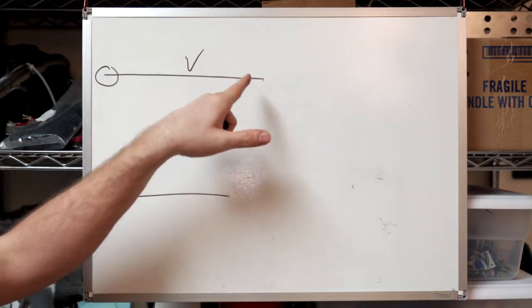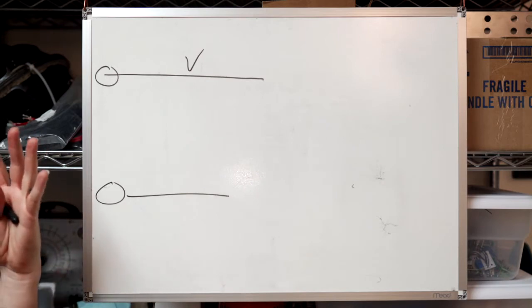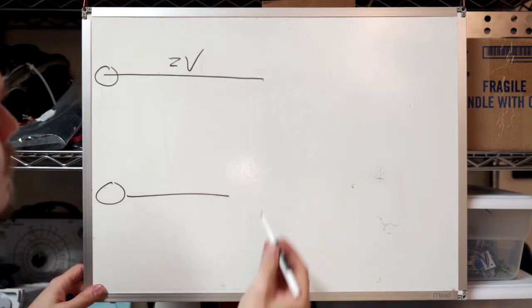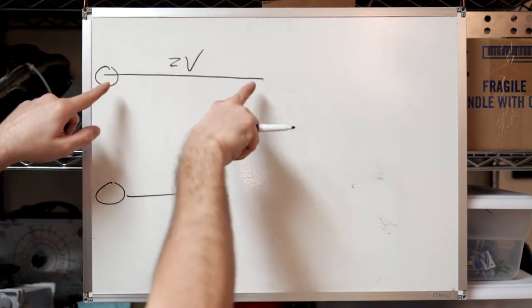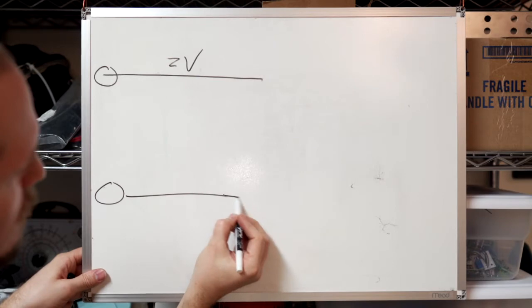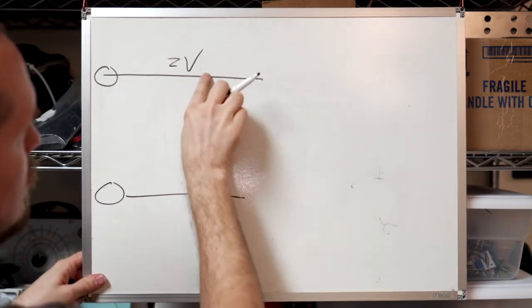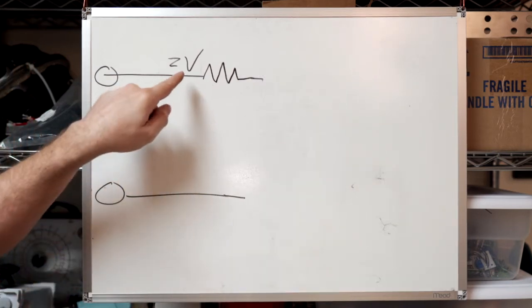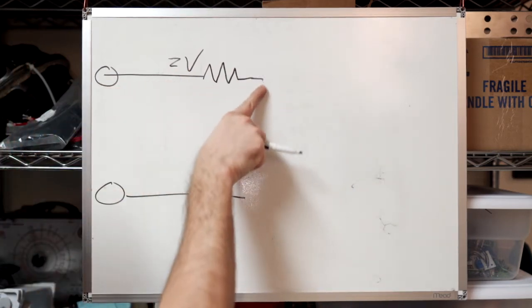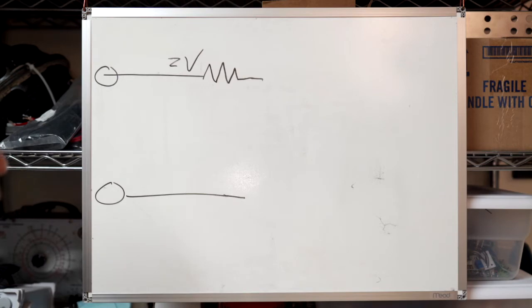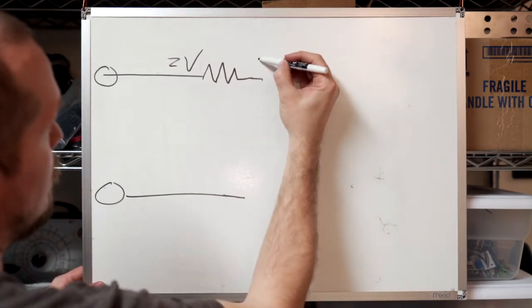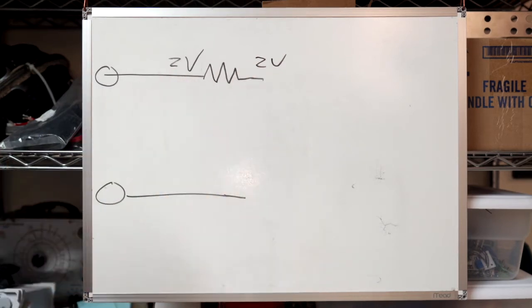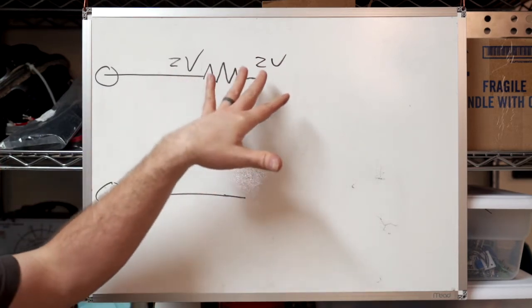And we've decided that we're just going to set the input of the amplifier so the output of the amplifier is 2 volts, right? So we'll just do 2 here. And when the amplifier is unloaded, now remember there's a series resistance here we're trying to find, right? Like that. But because it's unloaded, there's no voltage drop across that resistance, right? So it's going to be 2 volts here, like that. And so now we know that we have our 2 volts out unloaded.